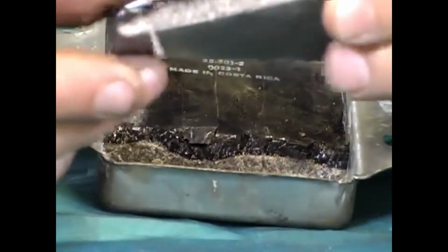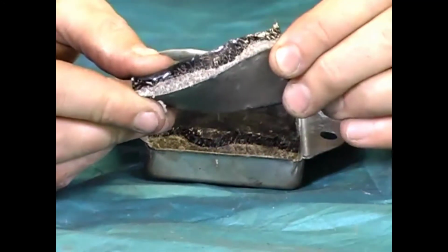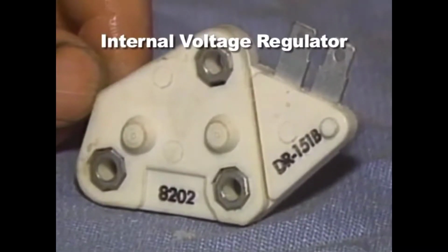The electronic regulator has the tiny electric circuit sealed in a protective gel. We have removed the protective gel to expose the internal circuitry of this regulator. Note how much smaller and simpler this is than the older contact point regulator. Here is a modern internal voltage regulator. It usually mounts inside the alternator. Some designs mount on the rear outside of the alternator.